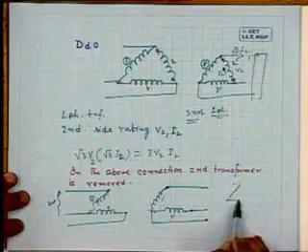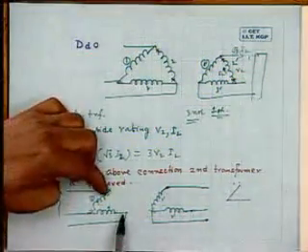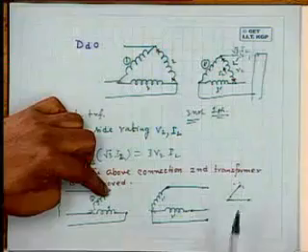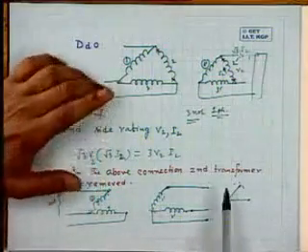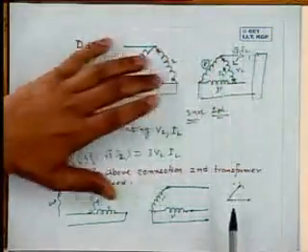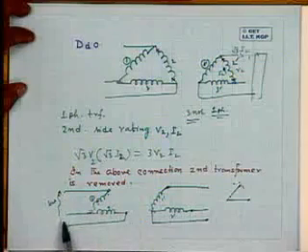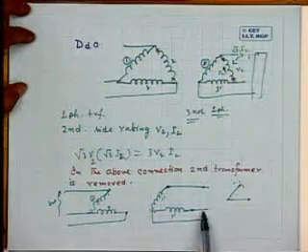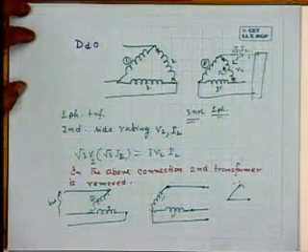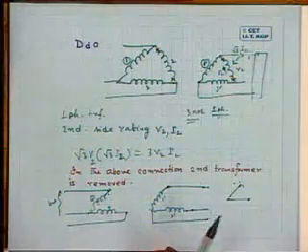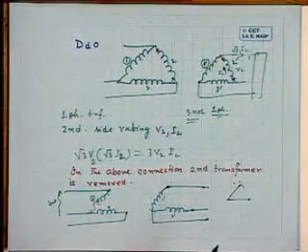Yes, you will get, because the input voltage is balanced. Okay. Although it is not there, if you connect a voltmeter between these 2 points, this voltage will be this one, resultant of these two. So whether you connect a transformer in position 2, 2 dashed or not, if you remove it, then if you apply three-phase balanced voltage here, you get three-phase balanced voltage on the secondary side. And there will be step up or step down depending upon the number of turns.